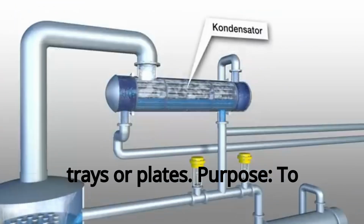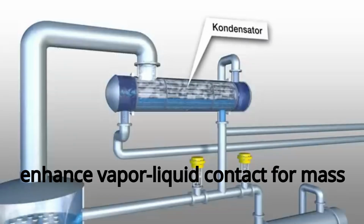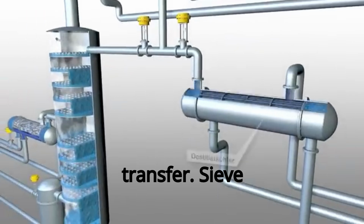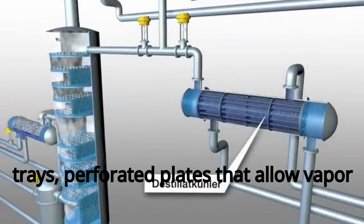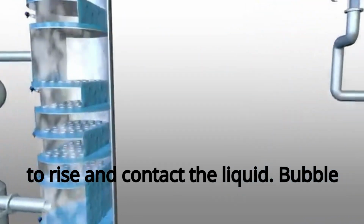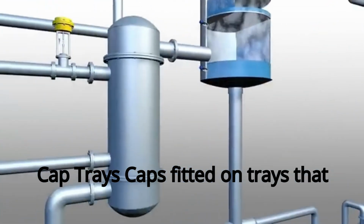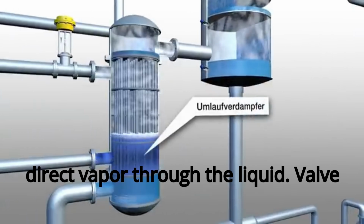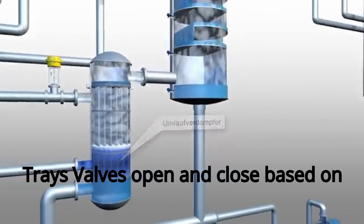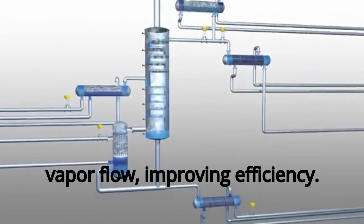B. Trays or plates. Purpose: to enhance vapor-liquid contact for mass transfer. Types: sieve trays, perforated plates that allow vapor to rise and contact the liquid. Bubble cap trays, caps fitted on trays that direct vapor through the liquid. Valve trays, valves open and close based on vapor flow, improving efficiency.